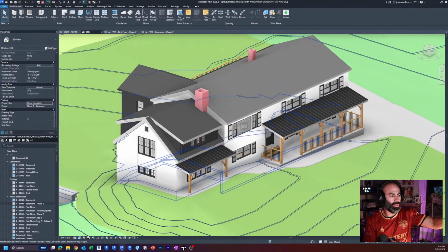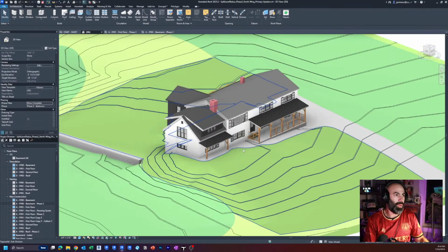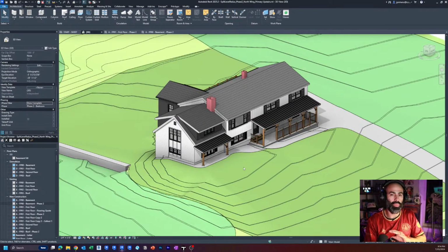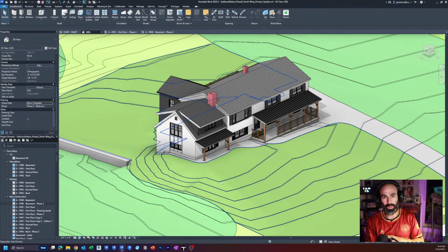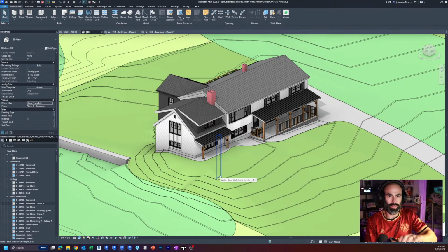So when you do Direct Link, you're basically forced, if I jump over here, you're forced to bring in whatever's on in your view, right? If you use Datasmith, you can bring in things separately. So what I can do if I really want to is export just my existing house and then the new one. Or what I would highly suggest, which I didn't do on this project mainly because it's an old scene and I just haven't felt like going back.